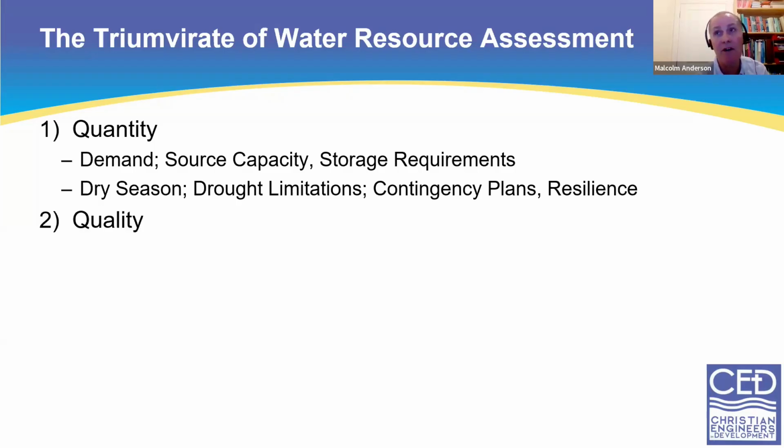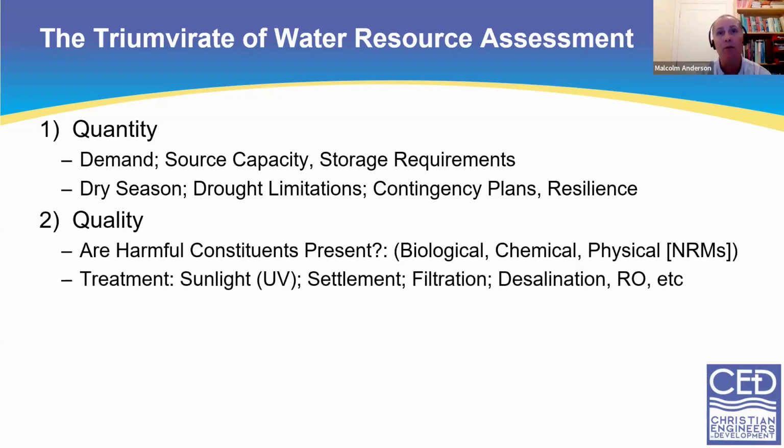And then quality is very important in groundwater well selection, because quantity is typically a function of the rock type that you're encountering, which will be true across most of your site in most cases. Quality, however, is very location specific. So you need to know where the hazards are, the water quality hazards. You need to know the direction of flow, and from that you can then work out where you can put wells in and where you can't. So quality is really important.